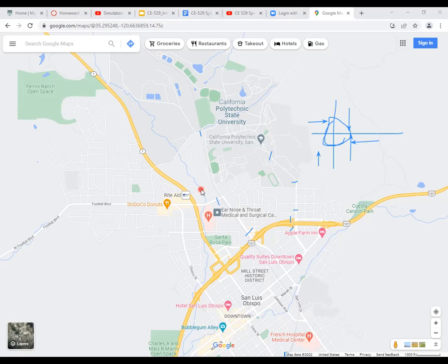So what you do is you make an OD pair assumption, and then you model your system. Then you compare it to the traffic counts that you have at these points and see if you're getting the right traffic. Is your model predicting the traffic that you see in the real world? Based on the origin destination assumptions that you made, are those assumptions getting you the traffic counts that are observed? If they do, then you have a validated model. If they don't, then you still need to tinker with your OD flow.